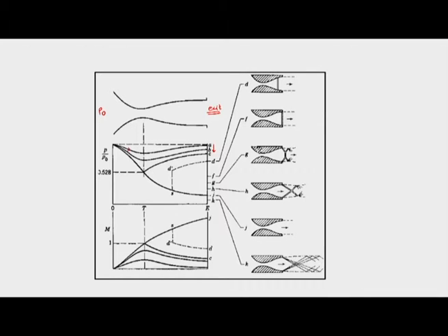We can see that pressure is decreasing, but once it reaches the minimum cross section, it encounters an increasing area. Since area is increasing, it is acting as a diffuser, so pressure is increasing, and this process continues till a point where we reach Mach number 1 for a particular exit condition. For that exit condition the flow expands in the subsonic nozzle and reaches Mach 1, but the pressure at the outlet is not sufficient to expand further, so pressure rises from there onwards.